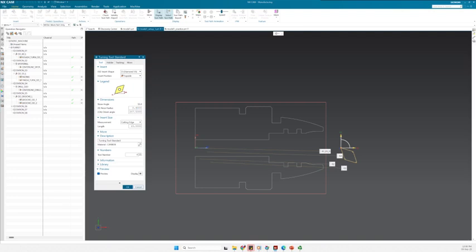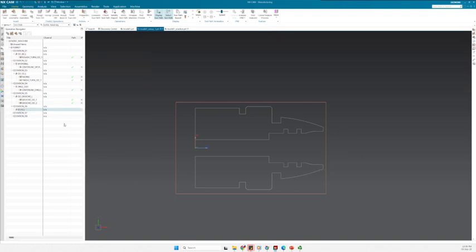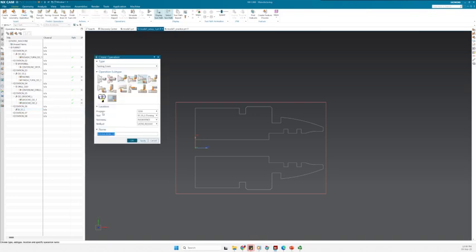Let's say our nose diameter is this much, so these are the values that I'm taking from, for example, a catalog. Then this one we can set, for example, to 4. So we have a smaller one, so then the holder would be able to go through. This tool number is correct. And now I have the tool here.